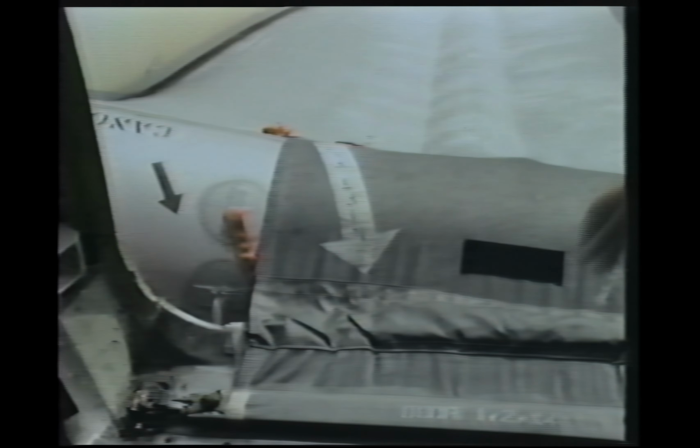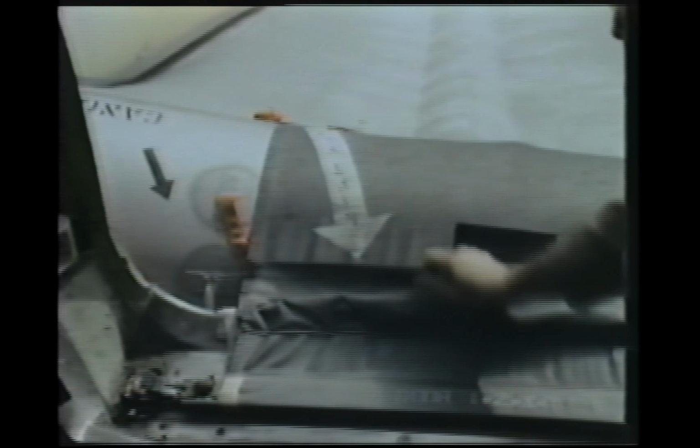If the slide rafts are needed in a water landing, make sure that the water isn't coming in around the door. If clear, open the door. When the slide raft inflates, load your passengers. And when ready to disconnect the slide raft from the girt, lift this flap and pull vigorously on the blue separation handle.